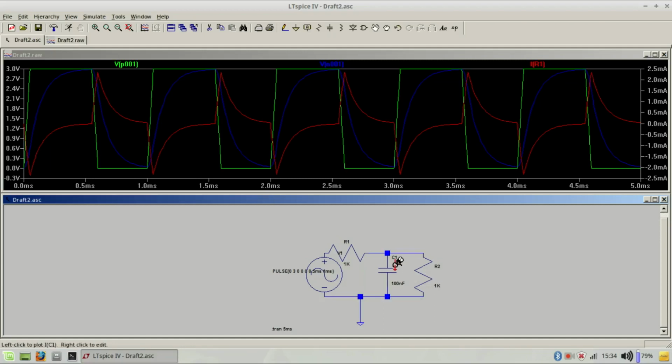Now our theory and our experiment on the board showed that the time constant, in this case, is nearly 1/3 of 0.5 millisecond, so it should reduce to somewhere here. It should reach somewhere here and reduce nearly half. And not only that, because of this R1 and R2, the voltage here will be half of what will be the applied voltage here, right? R2 by R1 plus R2. So now let us run and see whether that is true. So our prediction is that the blue line now will reach only to this point, and it will reach earlier than this, meaning somewhere here. So let us run.